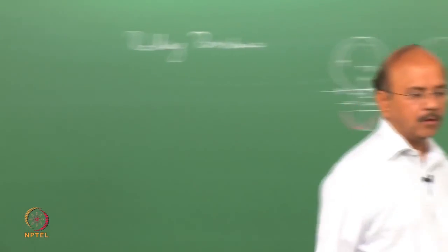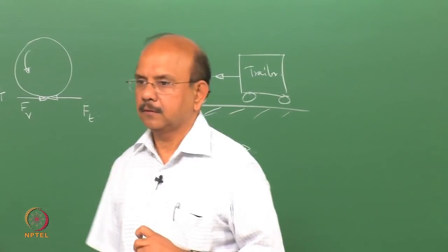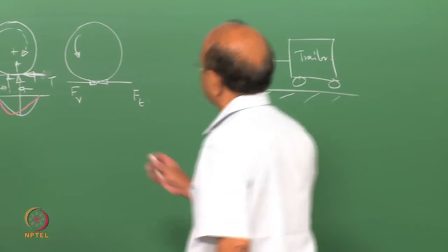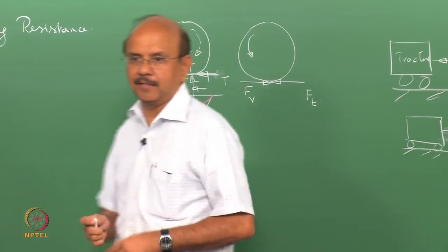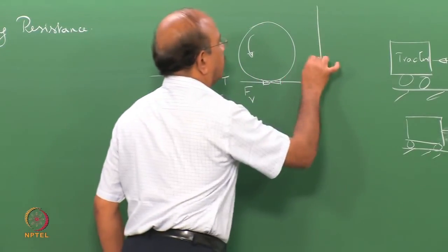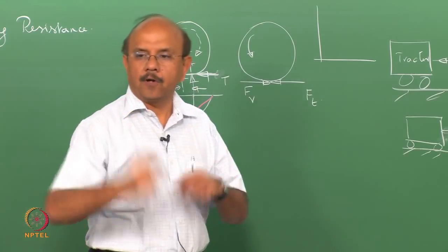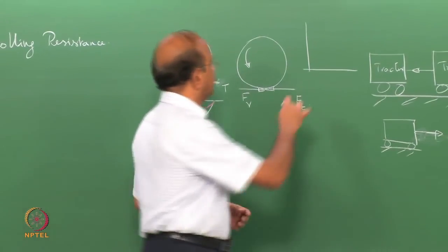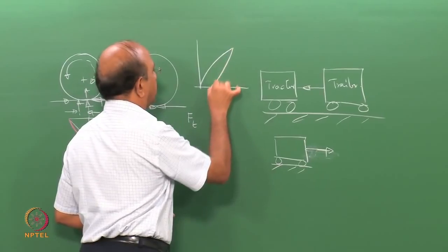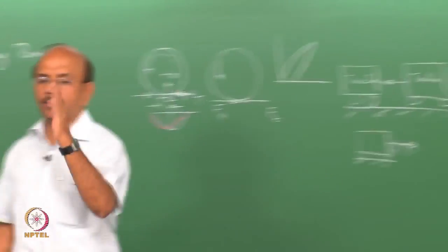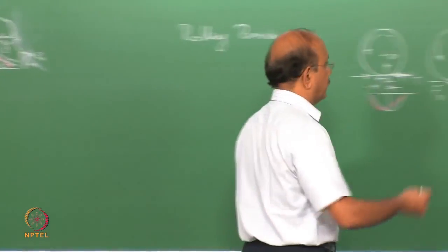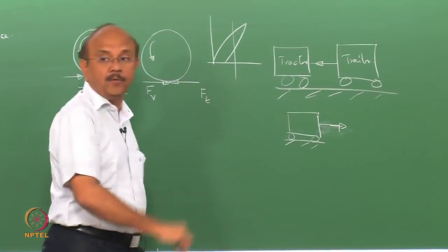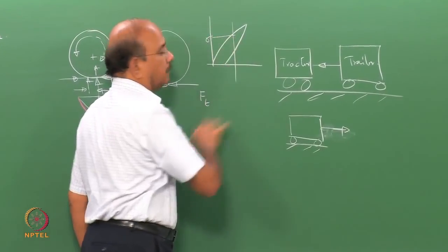Why will there be a shift? Yes, that is what we explained last class, that we will have a shift because of the viscoelastic effect, and that the loading, when the tread block goes through loading and unloading, the paths followed are different. One is loading and another unloading. So, for the same displacements, or the same strain, the forces, given by sigma, are different.